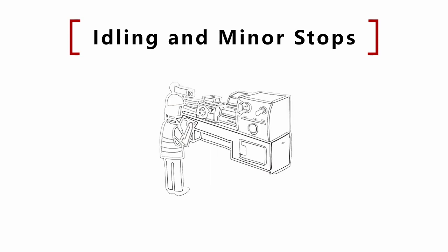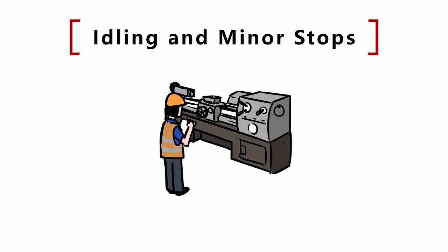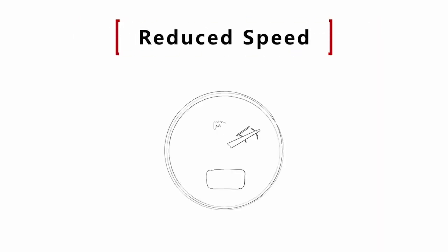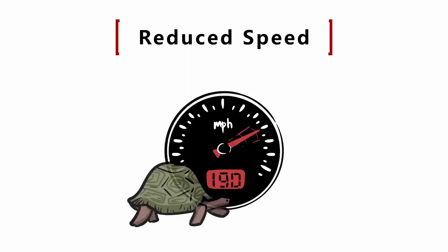himself and does not call for maintenance. This is a classic example of a minor stop. The sum of these minor stops, perhaps on several machines, can lead to a large loss of production capacity at the end of the shift. Reduced speed. Some plants, if not properly maintained, can meet the quality requirements only if they work at a speed lower than the nominal one.